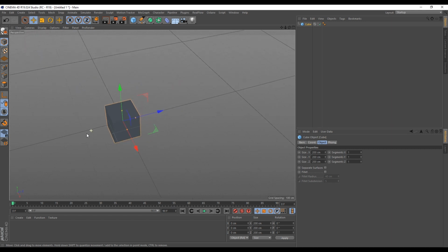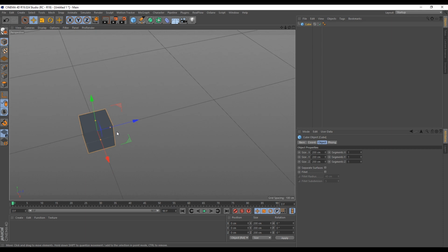Now, to practically understand keyframing, let's use this cube for demonstration. Now the task for us here is to animate this cube on the z-axis. So we want to move this cube from here to this point and then also bring it back, but we want this action to be recorded in our timeline. Now remember our keywords, frame or point in time. Here's our timeline, and this is where you can find your frames. So these numbers represent your frames, and as I move, it changes to different frames. So currently this is frame 30 as it highlights here.